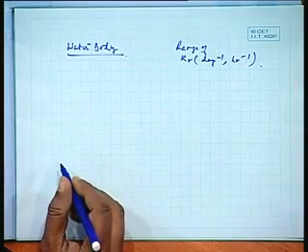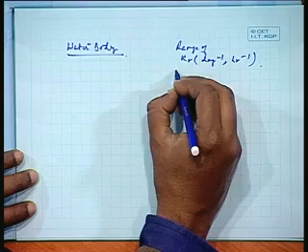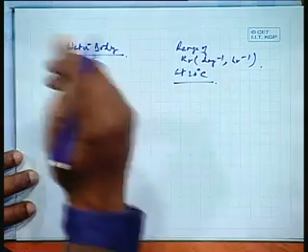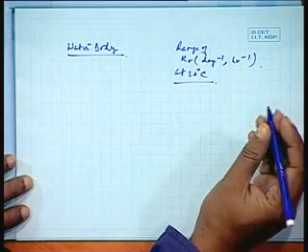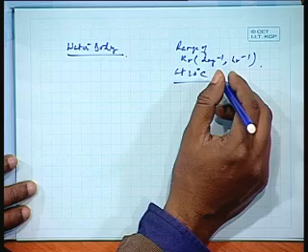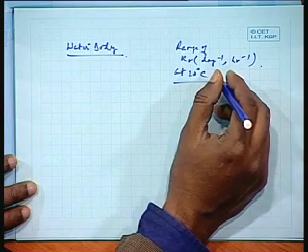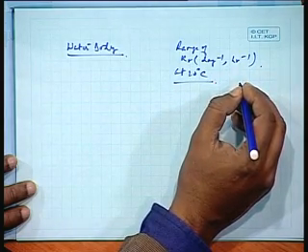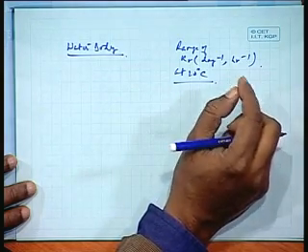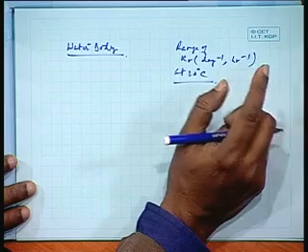this is the range that we generally observe, at 20 degrees centigrade. So, the typical adjustment that we have done in the case of a fixed water body also has to be done here if it is given for a different temperature, right. You remember that function that I have given, K_T is equal to K20 into theta to the power (T minus 20), that is, temperature 35 minus 20 is 15.